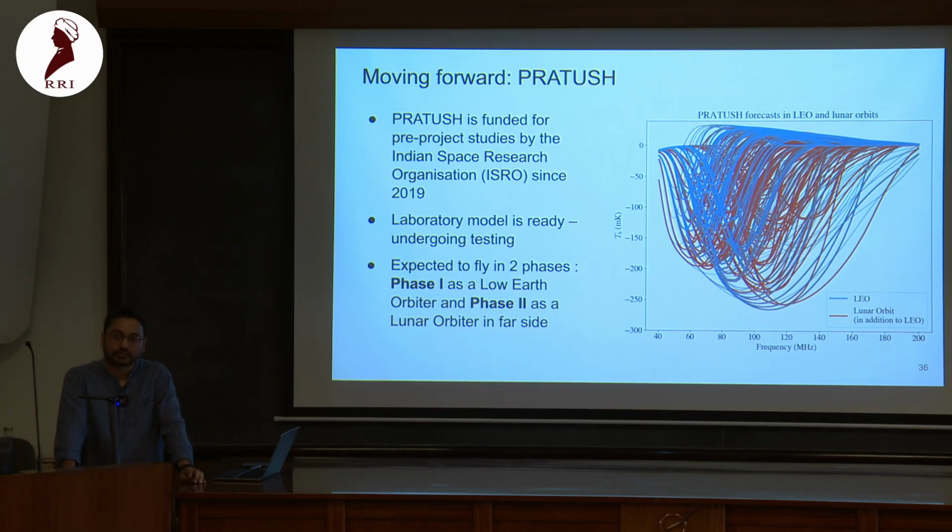And a related question is about your antenna beam pattern: you're not seeing the zenith. No. Any particular reasons that you want to comment on? Yeah, this is just the monopole's problem, which is that there is a null at the zenith. Ideally, we would want it to be looking at zenith so that the obstruction from the terrain is reduced. But with monopoles, it's simply not possible.